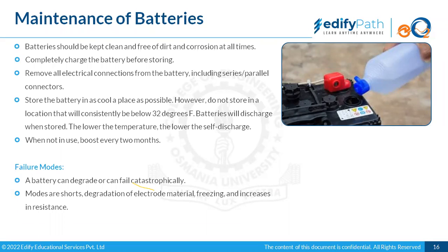Completely charge the battery before storing. This has to be taken care of, like charging and discharging should be happening. Don't discharge to 0%, but at least to 90% it should be charged. When you are charging, it should not be an intermediate charging, but it should be fully charged. You should assure that you are fully charging it and fully discharging it during use.